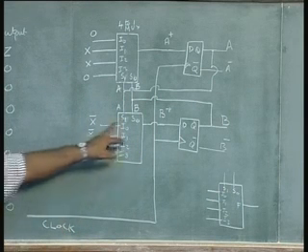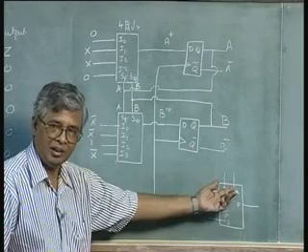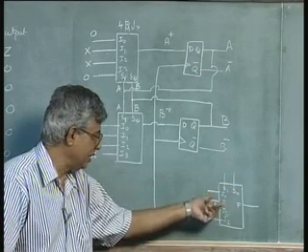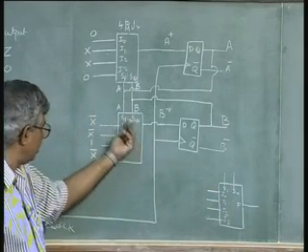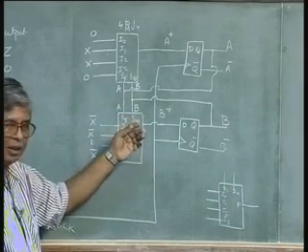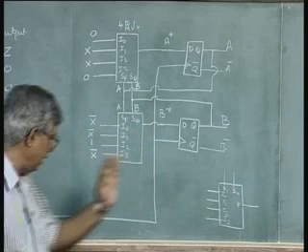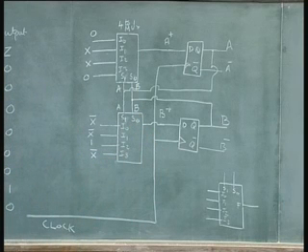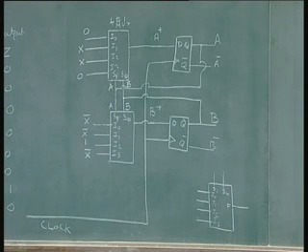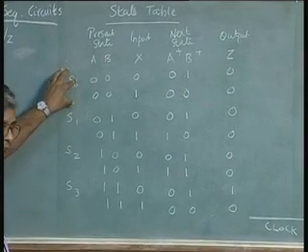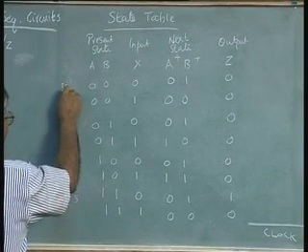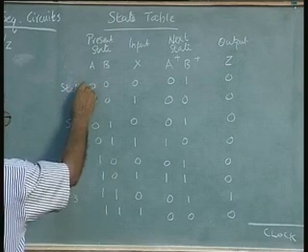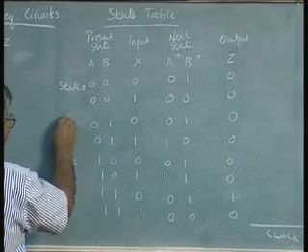That is why this S1, S0 came here, because these are selector pins, these are input pins, this is an output pin. So because of that, we got this S1, S0 interchange, but not to be confused with the S0, S1, S2, S3 states. We are not using it as in the equation, this is only to indicate the condition. So if you do not like this S0, you say state 0, so that you can completely avoid that confusion.